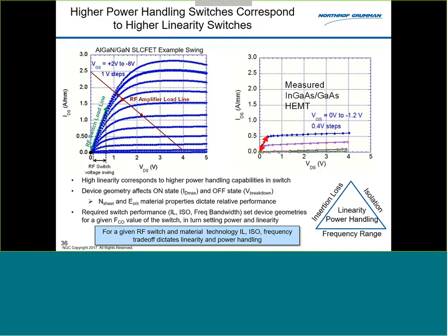GaN, yeah. So exponential gate current in GaN, if I just go on the market and buy GaN amps, absolutely. But that's because they're a MESFET structure. They don't have an insulator on these. So I'm using the same material, that gallium nitride, but in terms of the underlying structure, like what goes into that super-lattice, that's quite a bit different than a conventional device.